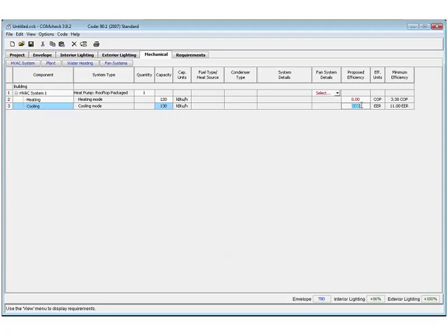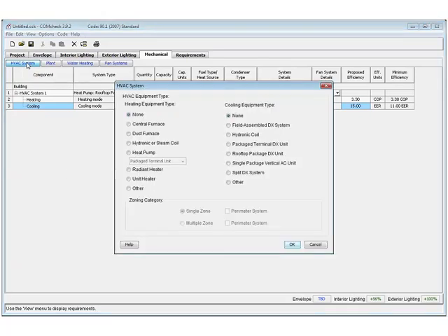And then your efficiency, maybe you're entering the same efficiency, or that efficiency might be better. So I could put in the same if I wanted, but you've got to enter it. It's in red. It needs that value. Or I can enter a better efficiency if I wanted. But now let's take a look. So we've entered one HVAC system. If I wanted a different system, I've got to click on that HVAC system button again. It takes you back to that main screen.